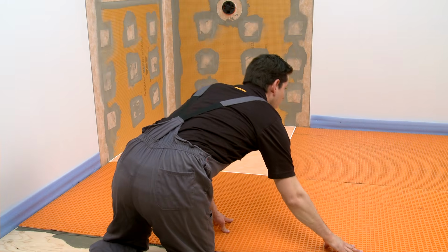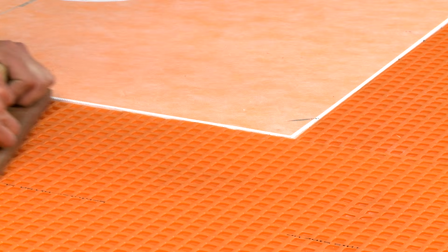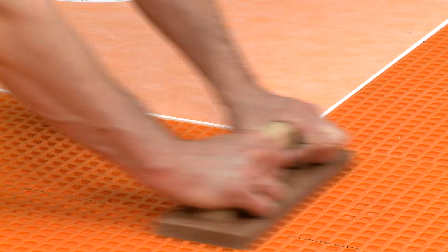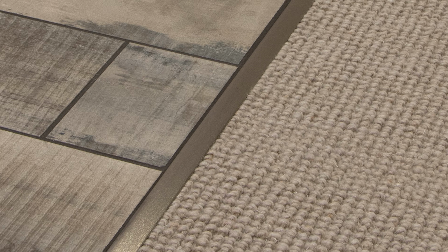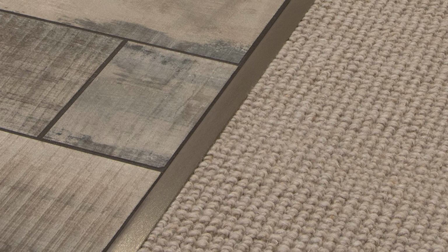When raising the floor, check the transition to the adjacent room before beginning the installation. The transition will typically be manageable when the adjacent floor covering is relatively thick, such as a carpet with pad or 3/4 inch thick hardwood.